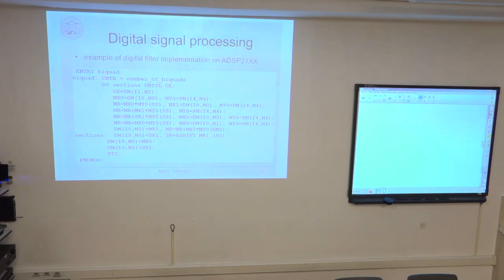done digitally. So practically AD conversion is done immediately after the antenna, preamplifier, or maybe after the first mixer. So you have the first mixer that transposes this spectrum band to some baseband, and this baseband is then sampled with this high sampling rate AD conversion. After that, instead of having an analog signal, you have a sequence of numbers. And this sequence of numbers is processed, but in this case in hardware, not in software, because the rate is too high to do any kind of software processing.